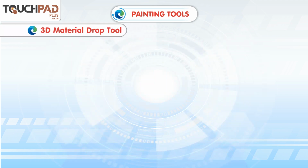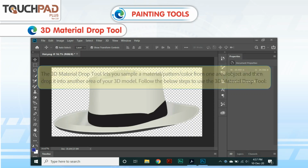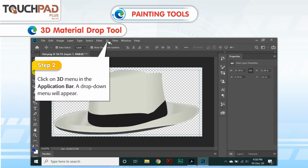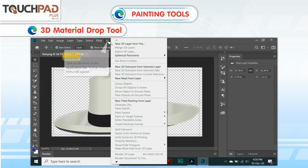3D Material Drop Tool. The 3D Material Drop tool lets you sample a material or pattern or color from one area or object and then drop it into another area of your 3D model. Follow the below steps to use the 3D Material Drop tool. Step 1. Create a new document in Photoshop and draw a gradient. Step 2. Click on 3D menu in the application bar. A drop-down menu will appear.